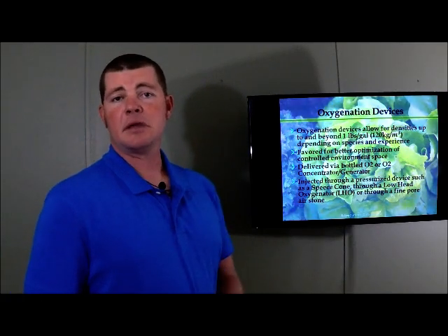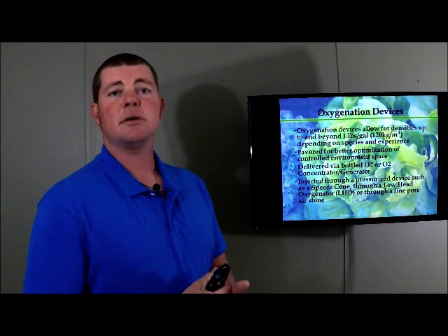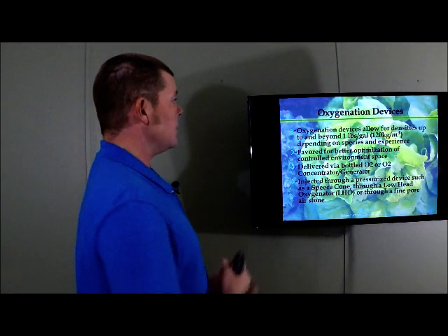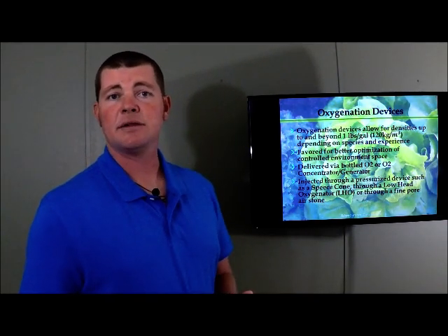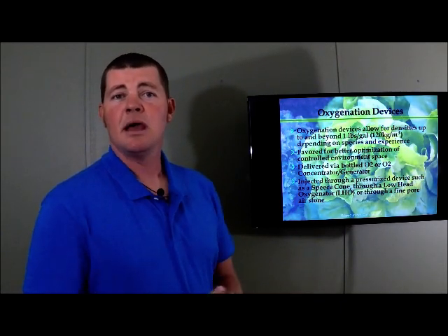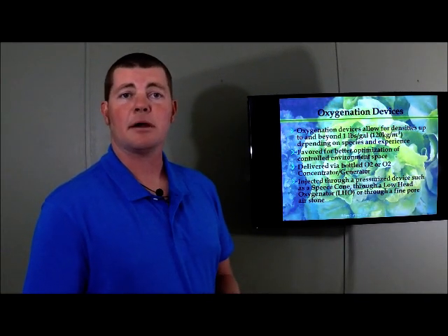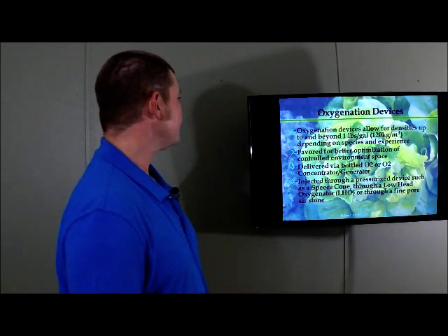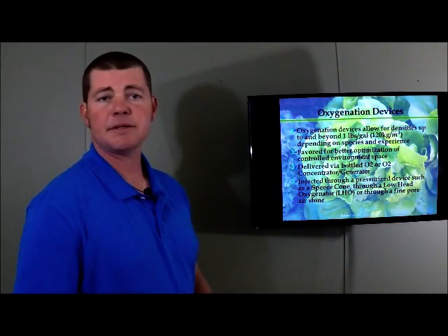So, a real easy way to think about this is that in the air that we're breathing every day, we have just about 20% oxygen. If we're using pure oxygen, we can get 90 to 99% oxygen injected into that water. So right there you can see that's roughly 5 times the oxygen that we can get out of atmospheric air, which leads to us being able to keep higher densities. So it's favored for better optimization of controlled environment space.